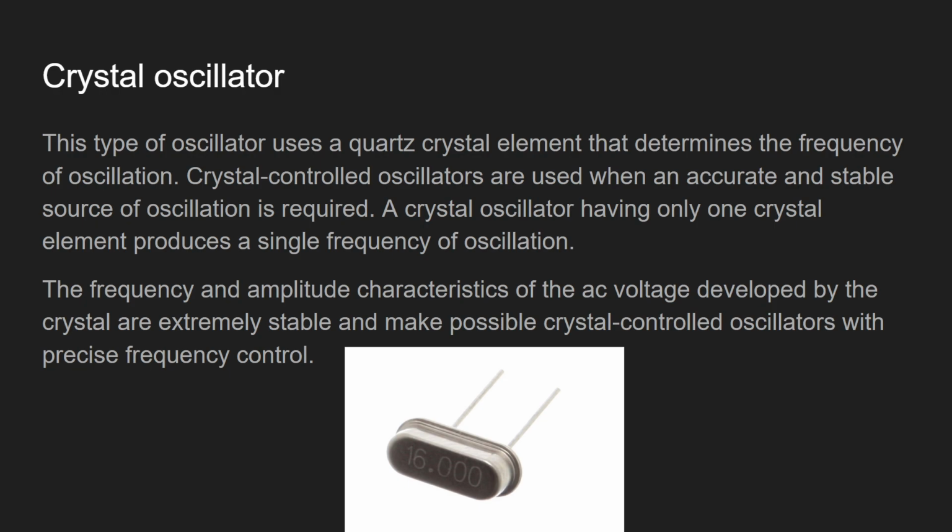Crystal oscillator. It is more important, and I want to spend more time on it. Okay. So you see, this is 16 megahertz actually. You can use a crystal oscillator to stabilize, and it's very accurate. So you just use a sharp razor to cut the quartz. You can control the thickness of the quartz to change its oscillating frequency. This is how industry does the work. That's why for this kind of crystal oscillator, they have different numbers here. It is about changing the thickness of the quartz.